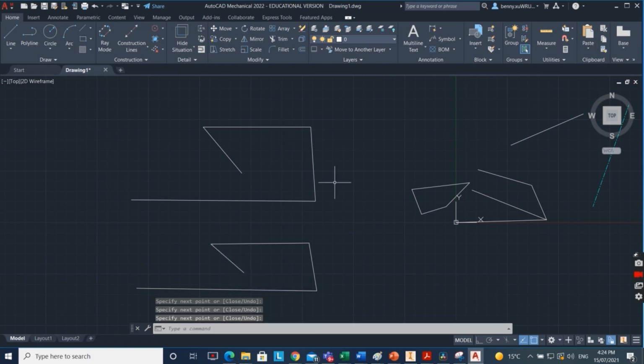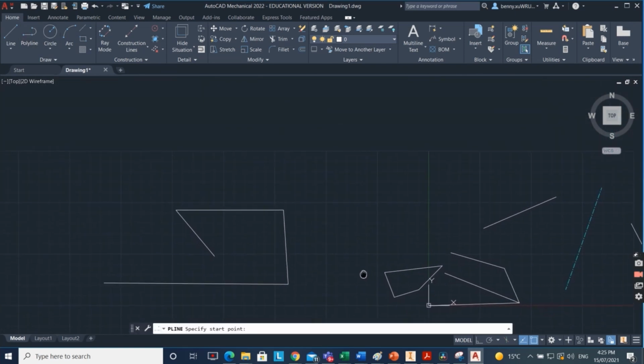They're very similar now. Okay, what's the difference? If I escape it, when I select this line, I just click on there and then I delete it. Now, if I come to the same position here in the polylines, and then I select the whole thing, if I delete it, the whole thing is going to be gone. So they join together, like a group of lines. And this one is not a group line. I can deal with this line individually. So that's the only difference. For polyline, I most likely use the other polyline, which is a curve line.